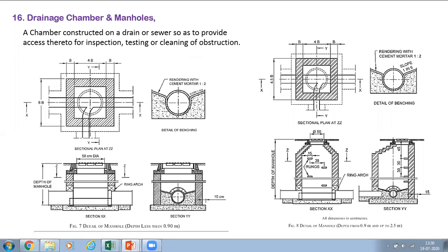Suppose your site has started, anyway you are going to take the pipe under the plinth beam only. You have to decide the plinth beam depth, everything. The minimum starting depth you have to give is 600 mm. That is the minimum depth for our pipe. Suppose there is any man movement or small vehicle, a cycle or bike movement, then 600 mm is enough, no problem.